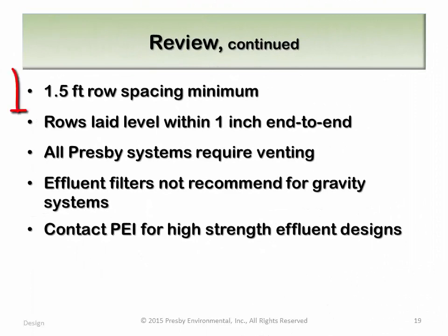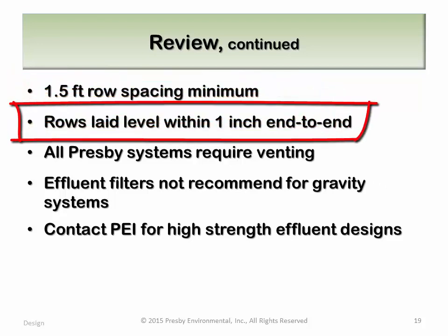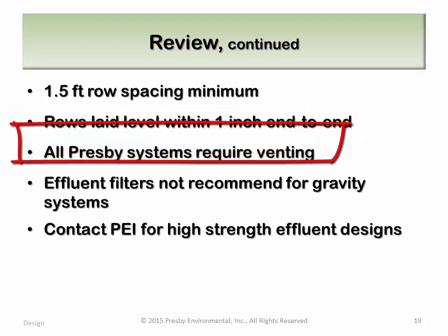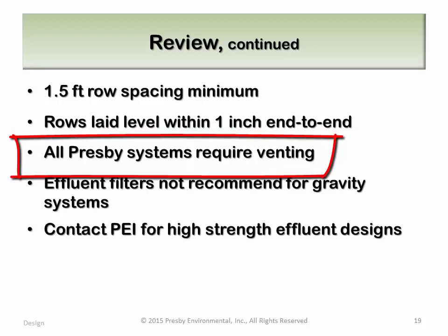Continuing with our review, 1.5 feet is the minimum center-to-center row spacing. The designer is free to increase this spacing if they desire. All Presby rows must be laid level, end to end, within a single inch. This is required regardless of the row length. All Presby systems must be vented. For multi-level beds, the vent must be connected to the lower level rows.